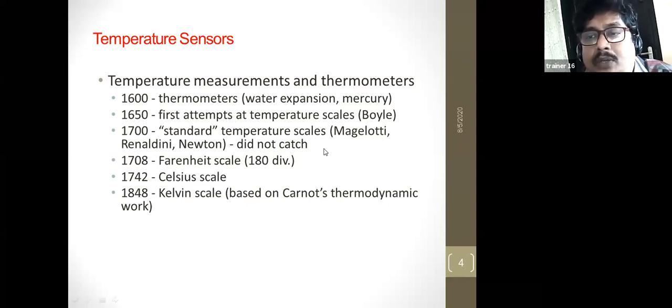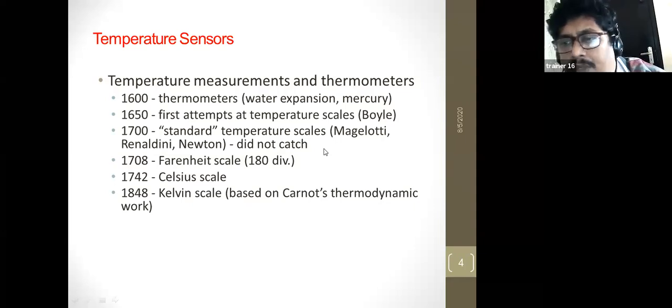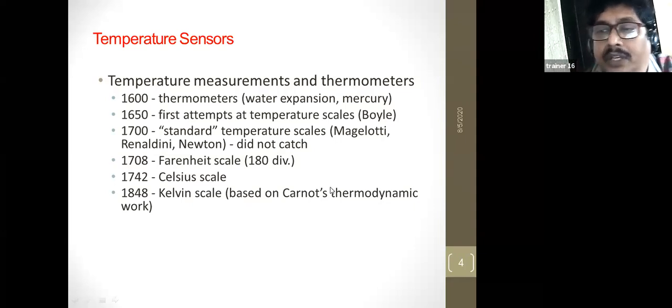So here, when the water reaches the high position, automatically the motor cuts off. When the level of the water in a tank falls to a particular level at the bottom, automatically the motor turns on. Thereby the water falls into the tank. It fills the tank up to a certain level. We can make that a constraint in the filling of water in a tank. There also we can use this level measurement device.